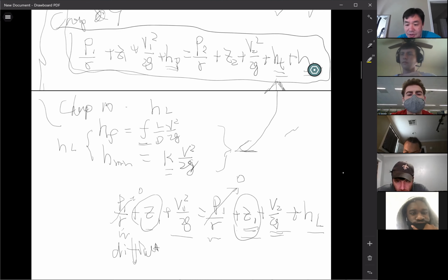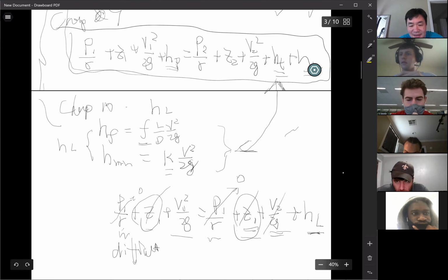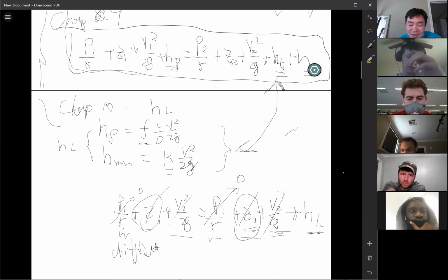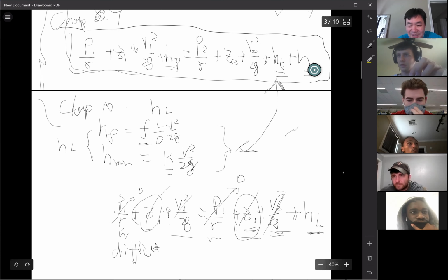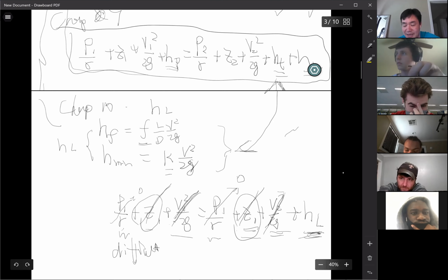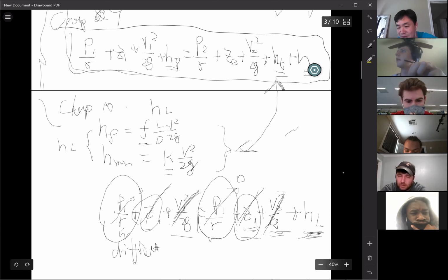Yeah, you can actually measure this by just looking at the pressure differences. For example, you can set the things equal to 0. Maybe that's a little bit difficult to measure. In Bernoulli, the velocity is the same for two portions of pipe, and maybe you can set the elevation the same. Basically, you can calculate the head loss based on the pressure readings if you have a pressure gauge.